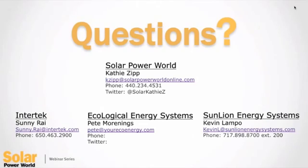All right. The short answer is yes, you can do that. However, it is better for the system to put the optimizers across the board. It is much easier to install. So any savings you're going to have on a couple of devices, you're going to throw away in the labor and the complexity of the system. So it's not a remediation against shade. From a holistic 100% of your install, it really does reduce the cost of the system versus just a plain old generic system.